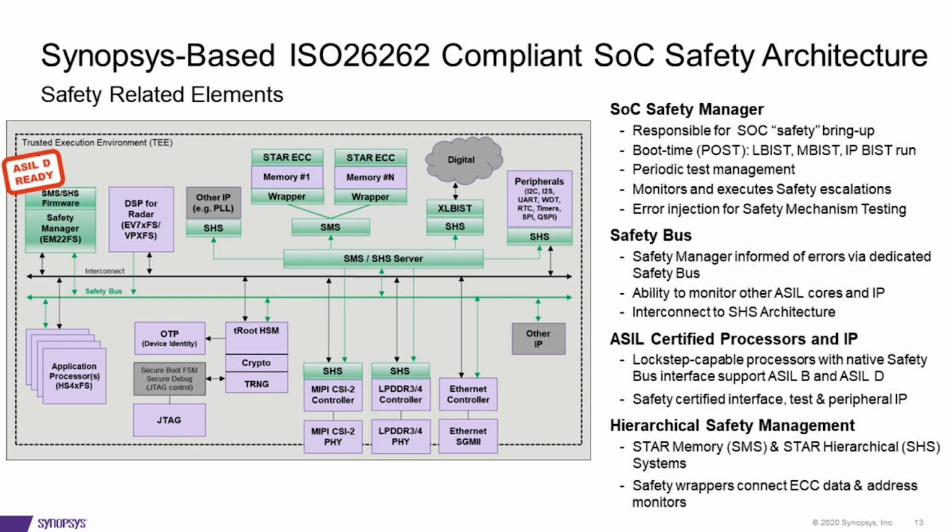One of the architectural aspects that we certainly promote within Synopsys is having a separate dedicated safety bus. To keep isolation between the functional and the safety-related elements, having a dedicated bus to escalate real-time safety errors is very important.